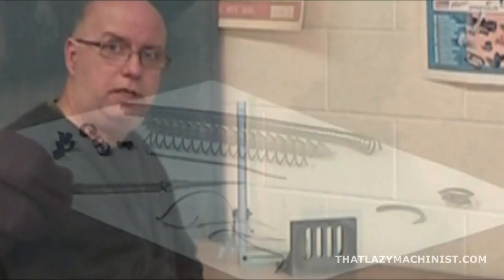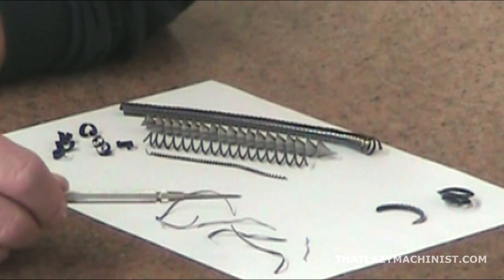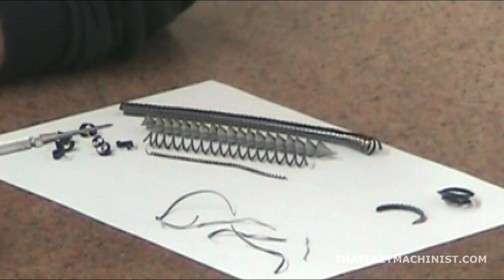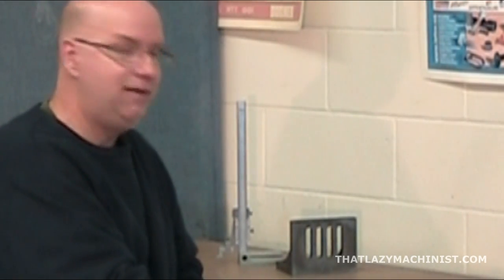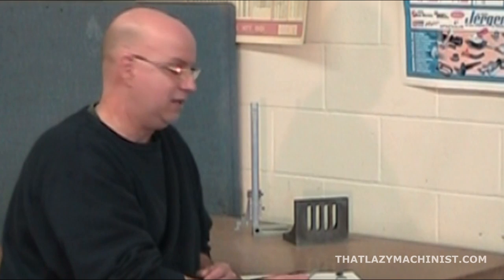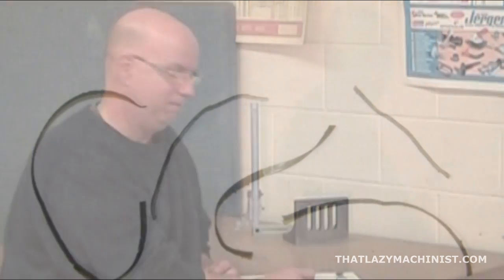The last group of chips, the ones down on the right side here, are our built-up or adherent chips. They are the result of an excessive amount of heat. If our discontinuous chips were hard on the machining process because of the excessive force and the vibration that they produce, well, these built-up or adherent chips are bad for the machining process because of the excessive heat.